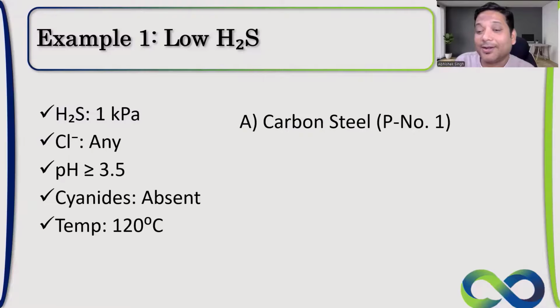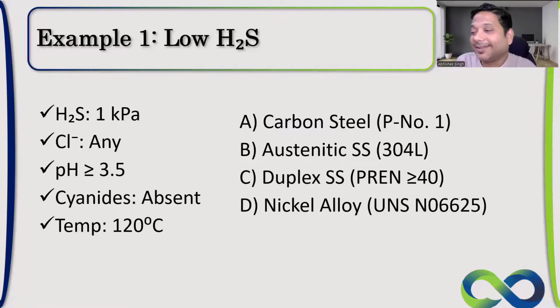Now, which material do you think will be good for this application? Low partial pressure of H2S, any amount of chloride, pH value more than 3.5, no cyanide, temperature 120 degrees Celsius.